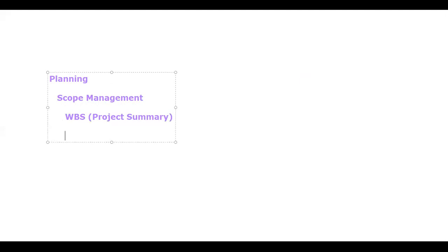So what is WBS? You have to break down your project into subcomponents. First of all we have to define what kind of project contract type we have. The mega project contract is EPC. So I'm going to divide my project first into EPC, meaning design, procurement, and construction, the first level of my project WBS. I'm going to share a process flow diagram on how to make WBS in your Primavera. First of all, you have to click on project in your Primavera.